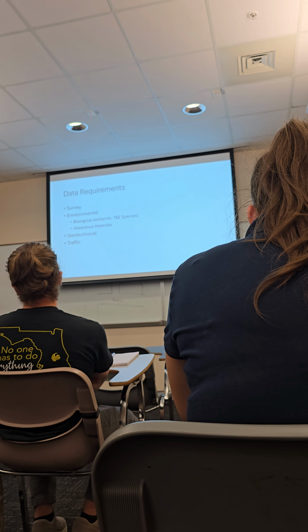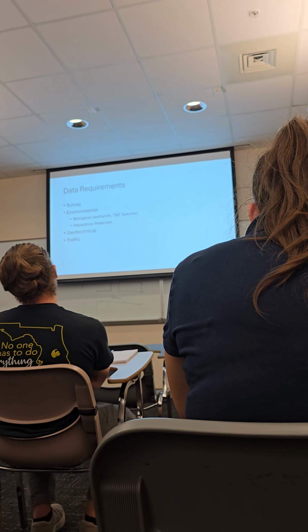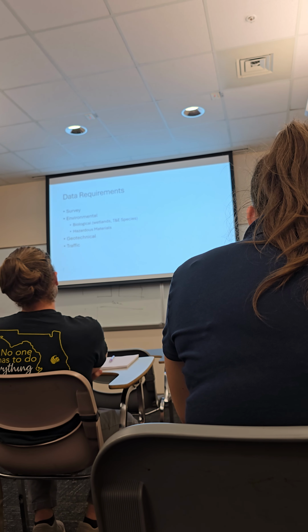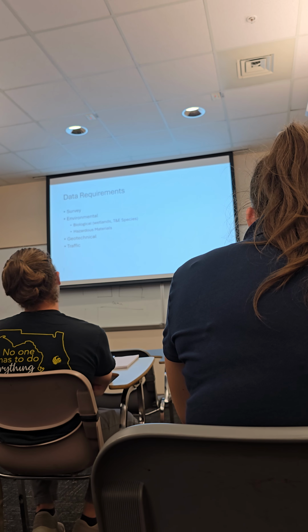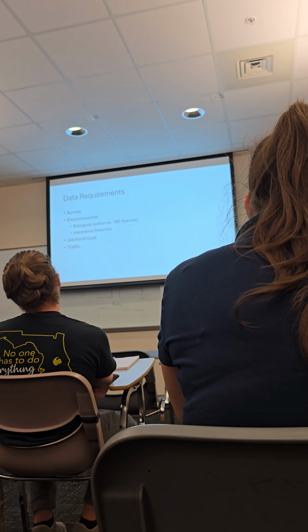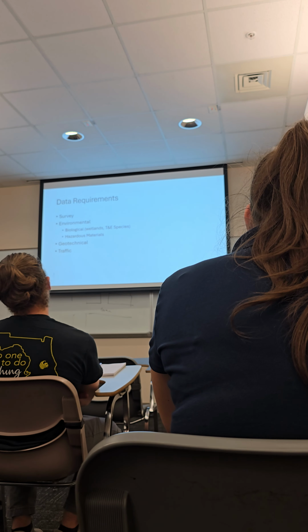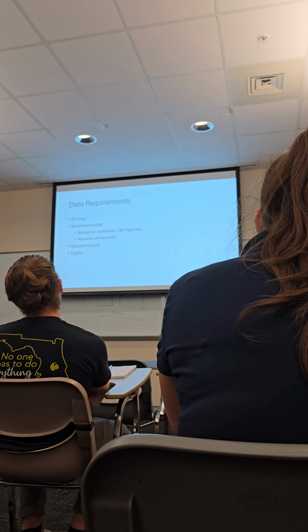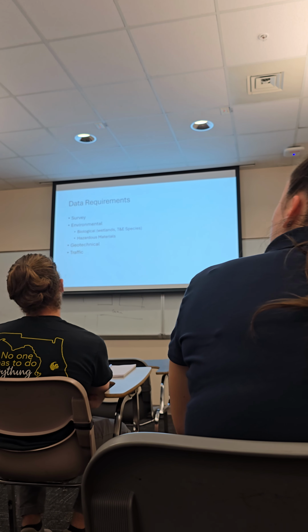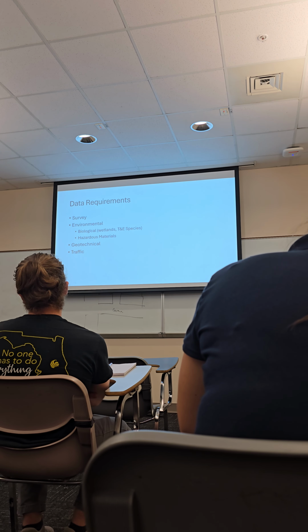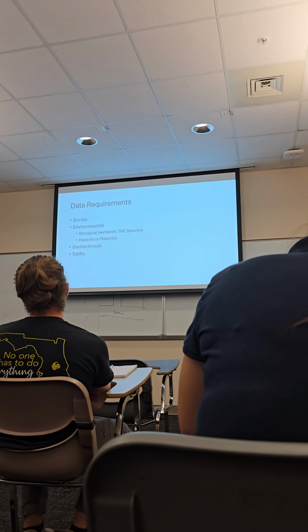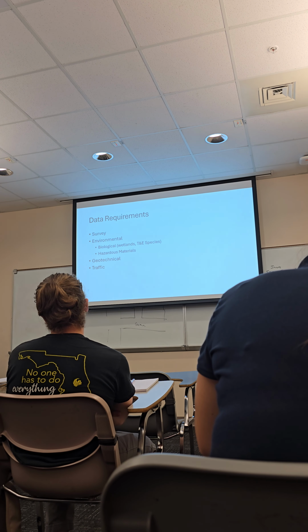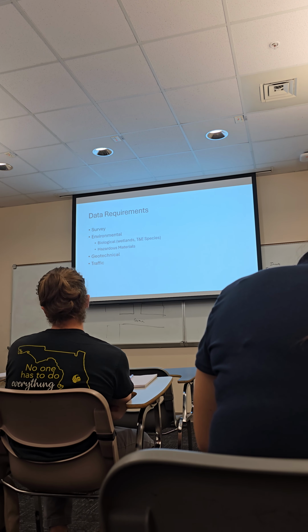So typically on a site, when you start a project, you would do an environmental assessment, and part of that environmental assessment would be to screen your site for any hazardous materials. So, for example, years ago I worked on a project and we discovered arsenic on the site. We were going to construct a pond. So that was a challenge. We had to figure out a way to remove and dispose of the arsenic to a certified landfill. So you have to process that through DEP.